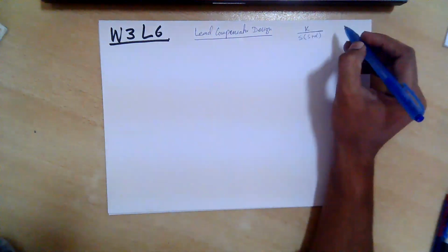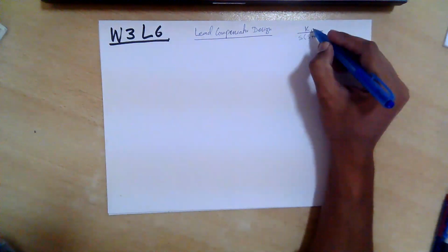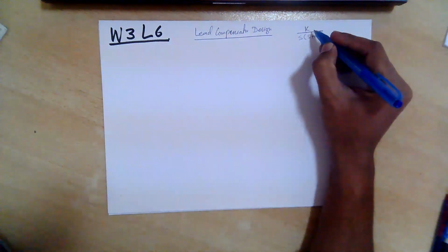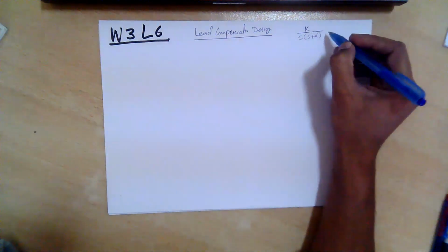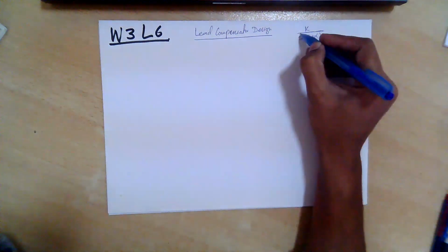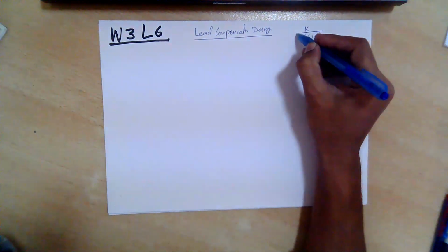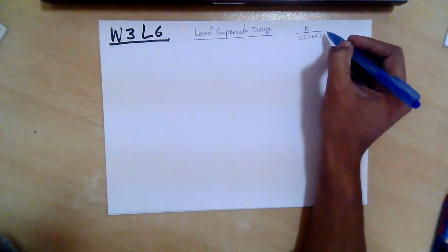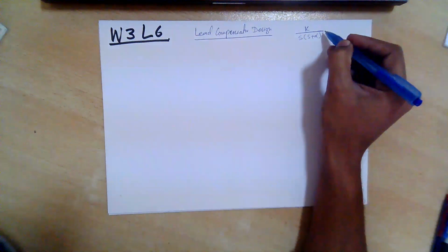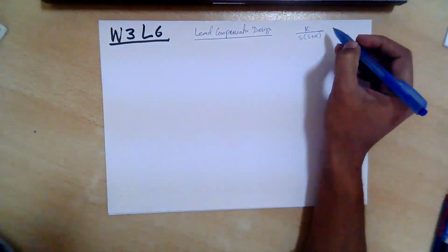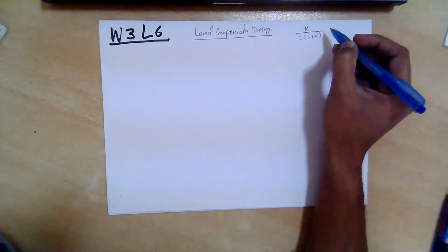We calculated the value of k based upon the requirement of the error constant, and after satisfying the error constant, we calculated the phase margin, and compared that phase margin to the required phase margin, and the deficient phase was added using a lead compensator.